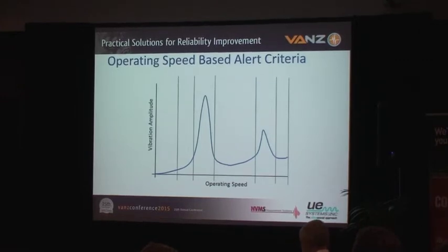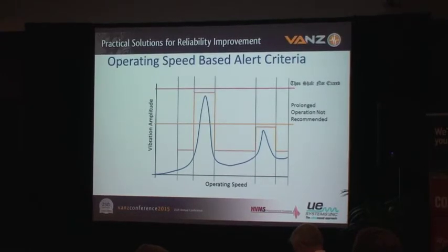And I think we can all agree and recognize the fact that when we start chunking up the operating states of the machine into specific speed ranges, in the case of this scenario, we can then start to apply, or we can put back the other thresholds, but now we can start saying, I want to alert or alarm on this machine when it's in this speed range at this amplitude, but if it's in another speed range, I want to alarm and alert at a much lower amplitude.